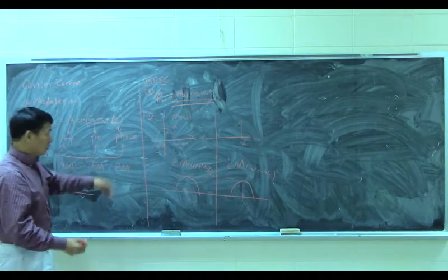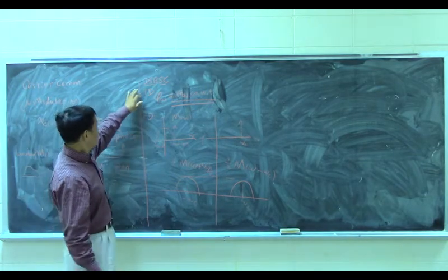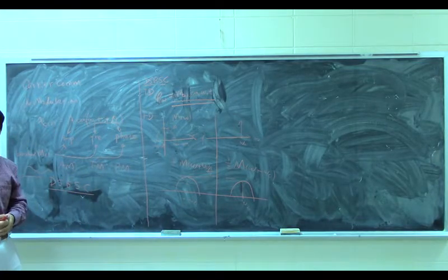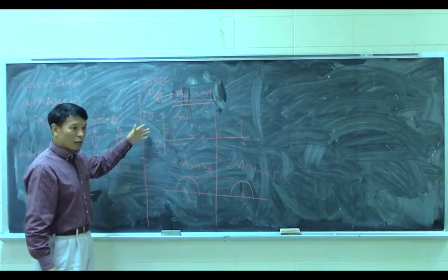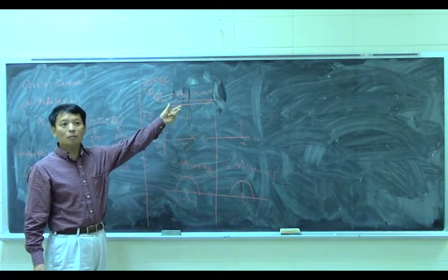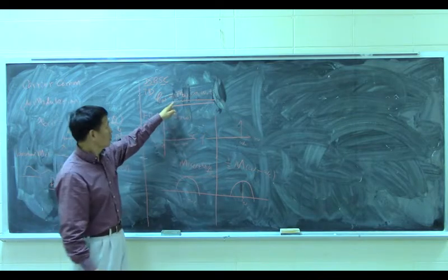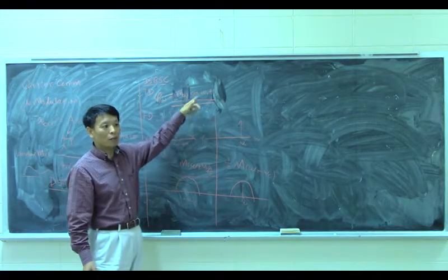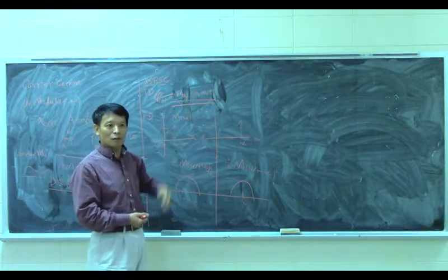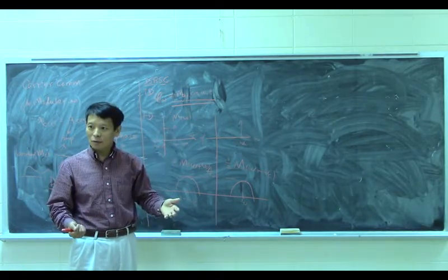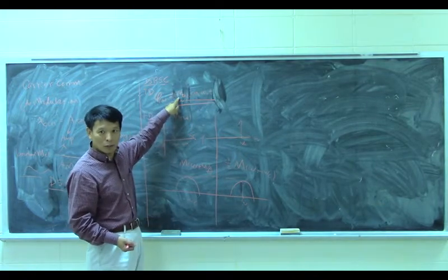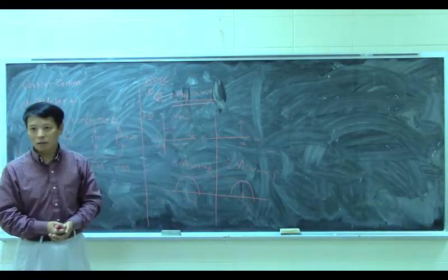Okay, now let's summarize. What is the AM modulation here? If we look at the AM process in time, what is it? It is just a multiplier. You use the baseband information and multiply by your carrier signal. That's it. As simple as this. Any questions? So in time domain, just your baseband information you want to transmit, multiply by the carrier signal.